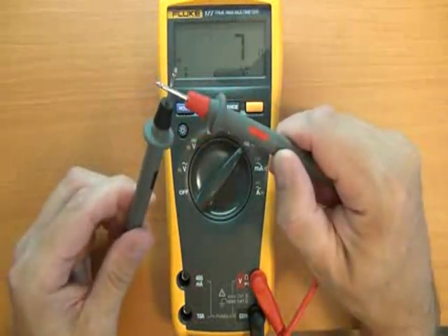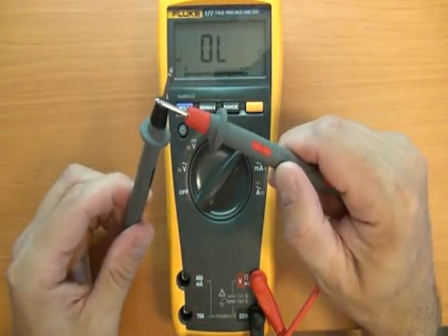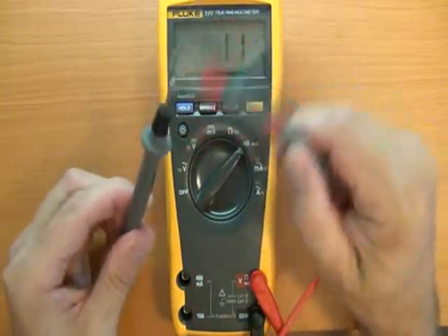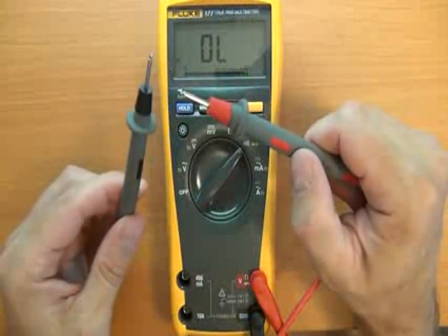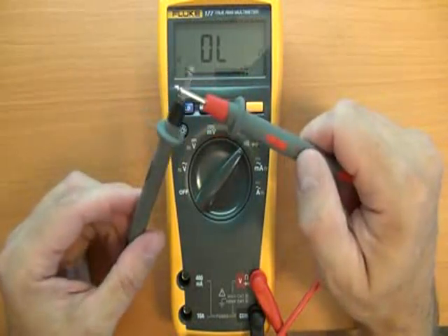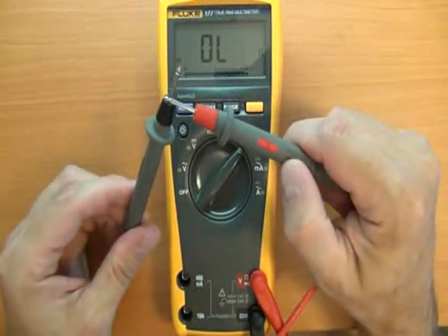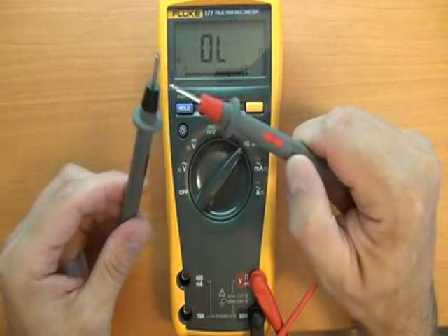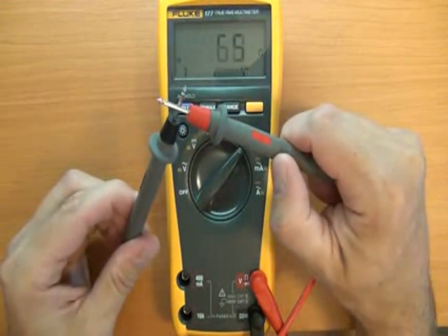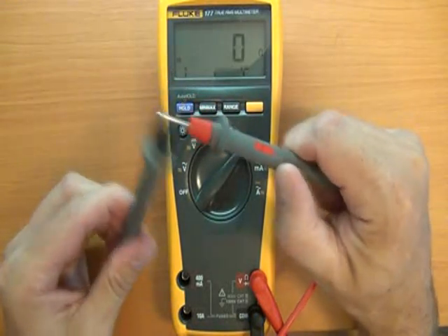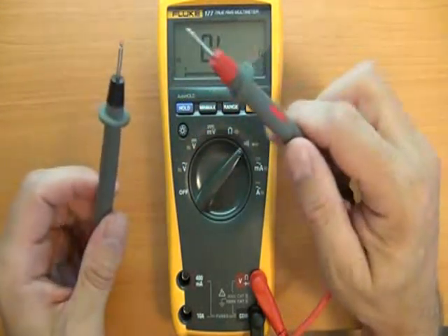But the Flukes generally have a latched continuity tester, which is very quick and clear. And if you're a more serious user of a multimeter, that can be very critical and useful, especially if you're checking small electronic components. So it's just something I want to highlight. Having a good continuity tester certainly adds a lot of value.